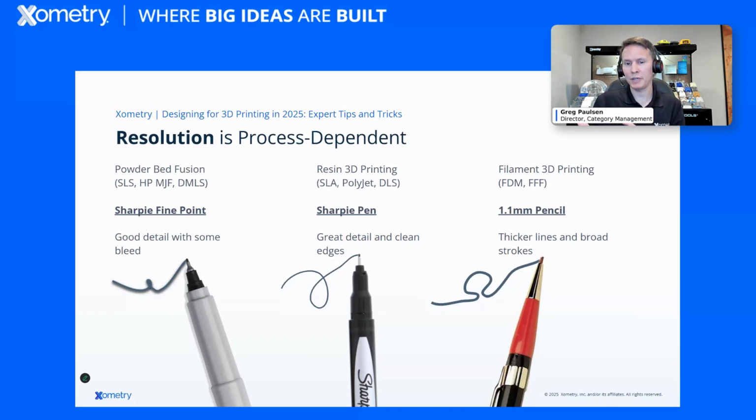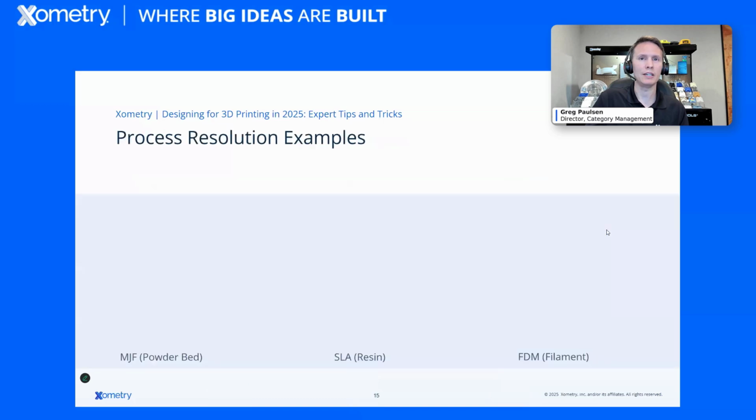And then lastly, filament-based 3D printing can sweat the small stuff. So I don't even loop on this, right? I kind of go close together and pinch and then move out. I am zigzagging a melted filament back and forth to create my layers on a layer by layer basis, and with that, it has more coarse features. But one of the great things it can do is build large, broad mechanical structures really well. But if you have something that's very high detail or has very fine features, they may be sacrificed. And I'll show you what I mean in just a second here.